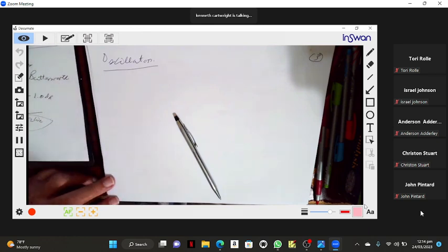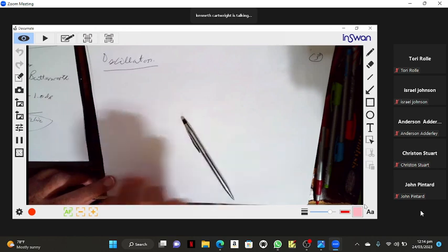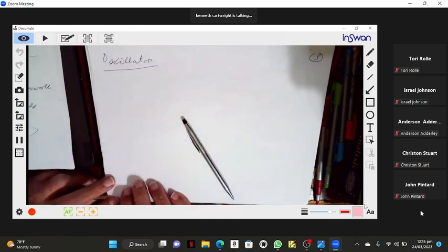That squealing sound is a sine wave being generated because the signal at the speaker is going back to the microphone in phase, so we have a positive feedback system, and that's what is causing that sine wave to be generated.